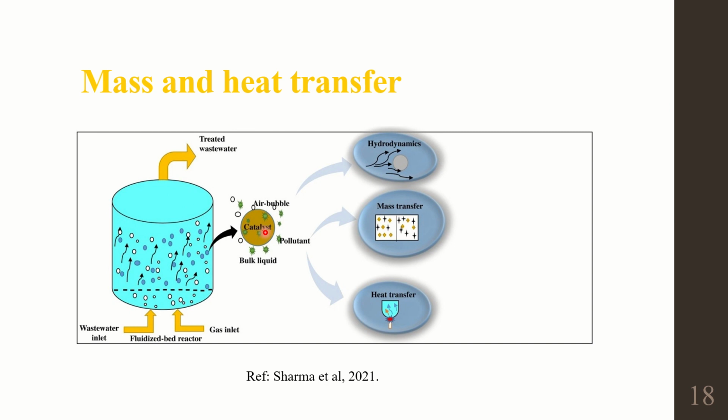The bubble is the void region, and the cloud is the surrounding region near the bubble. Inside the bubble the solid fraction would not be there, almost 80% of the bubble would be occupied without solids. So the bubble to cloud and cloud to emulsion interface mass transfer needs to be studied when we are dealing with mass transfer phenomena inside the fluidized beds.